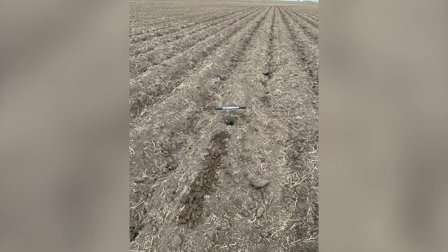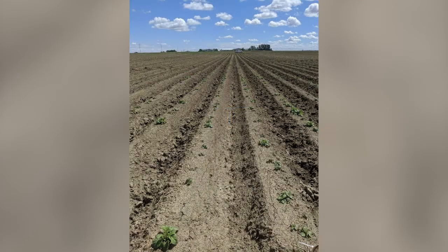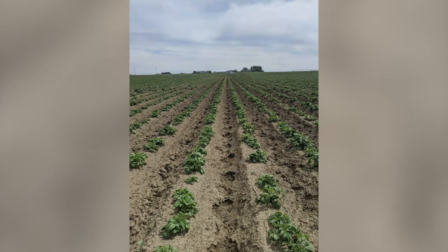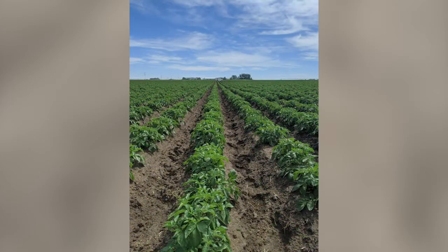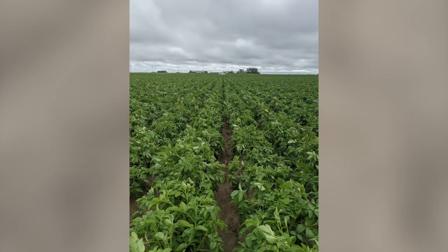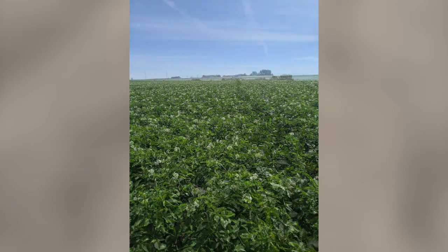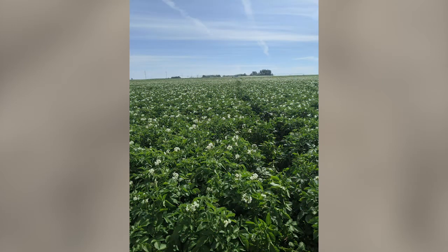The crop growth stage is a main factor in determining how much of the reference evapotranspiration the crop actually needs. A smaller plant needs less water than a plant in full bloom. However, with a large portion of the soil bare when plants are still small, irrigation in this growth stage will have to address direct evaporation of water from the soil.